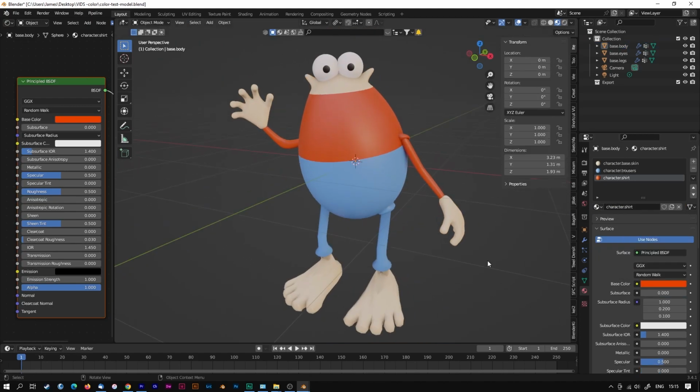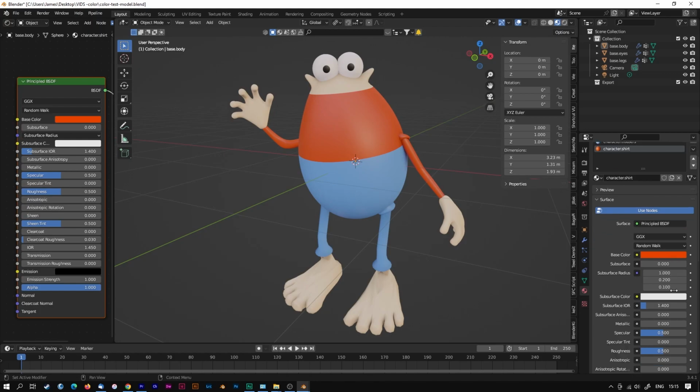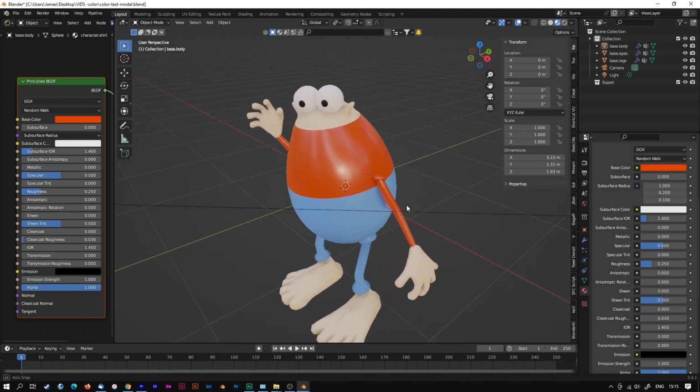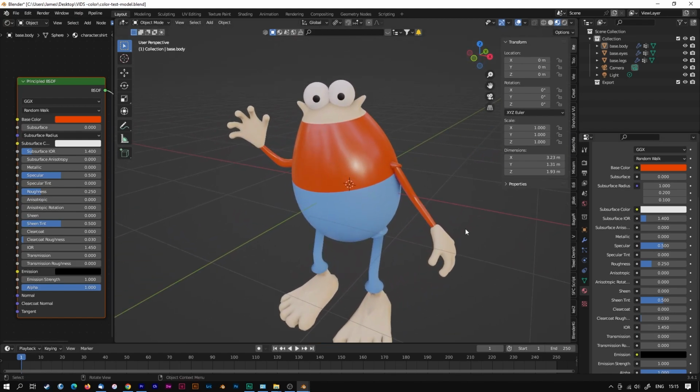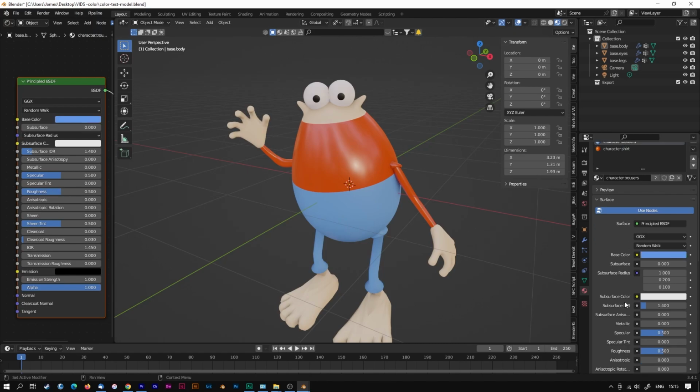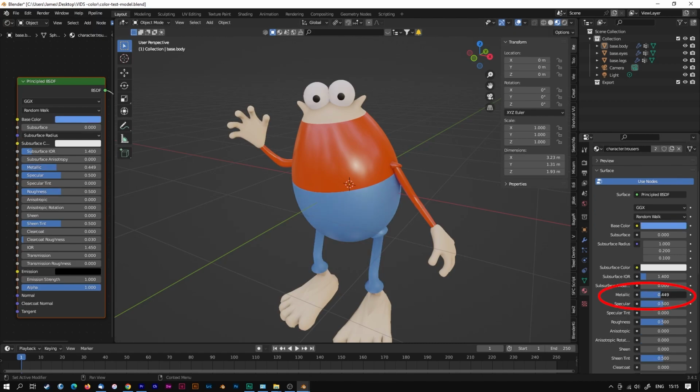There are many other things we can do within the Materials tab. For instance, we can change our material's roughness and glossiness by left-clicking and dragging the roughness bar over here, either to the right or to the left. We can do this numerically as well, with a single left-click and typing in the desired amount. As with all numerical values within Blender, hit Enter to commit. We can even make our material look metallic by sliding the metallic bar over here.